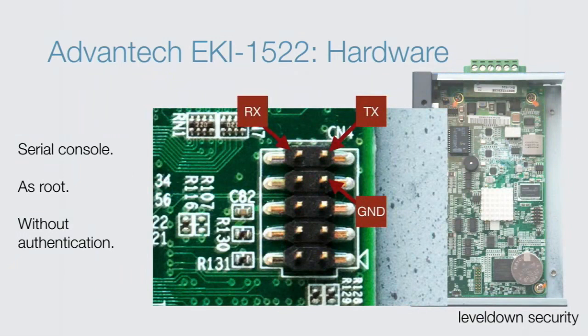And again, the file system and so on on these devices are not read-only. If you change something on the file, for example, you can buy it from a distributor, modify the device via the serial console, send it back, and they will happily resell it. We've tried that with the allowance of a distributor: we got a device from them, modified it by creating a file, sent it back, and ordered it again. And for sure, we got the same device precisely again with our modifications. So we actually have supply chain issues because of these serial consoles and because there's no way to actually authenticate the device and check whether it's been tampered with or not.